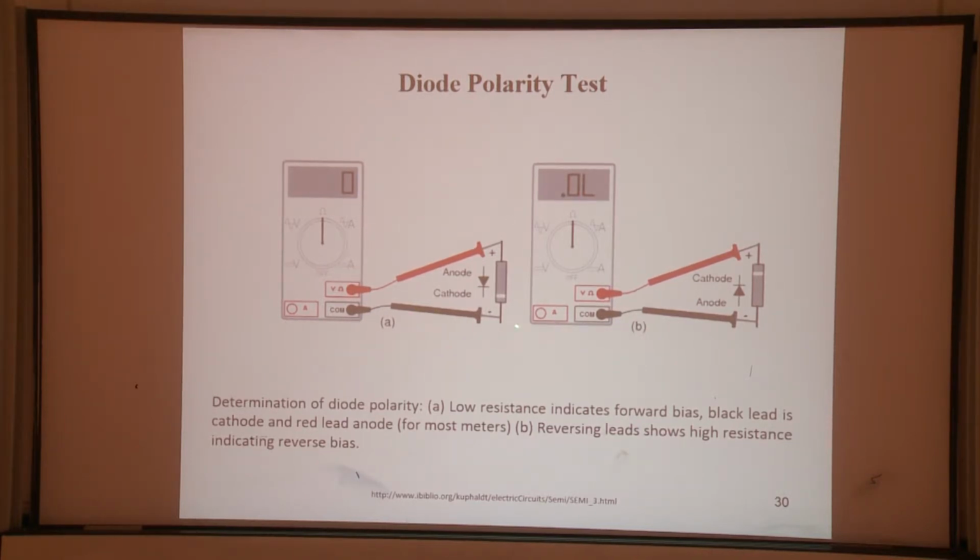So if you connect to the COM and you measure the resistance, right? You dial this to the resistance function and put the positive to the other side. Then it will be conducting or non-conducting. Very conductive. So the resistance shows almost zero. All right? Now, if you put that oppositely, then it is high resistance, hardly any current going through. The resistance is so high that it exceeds the range the multimeter can handle, so it shows something like an error. Overload. Good, good. Okay, now I know.